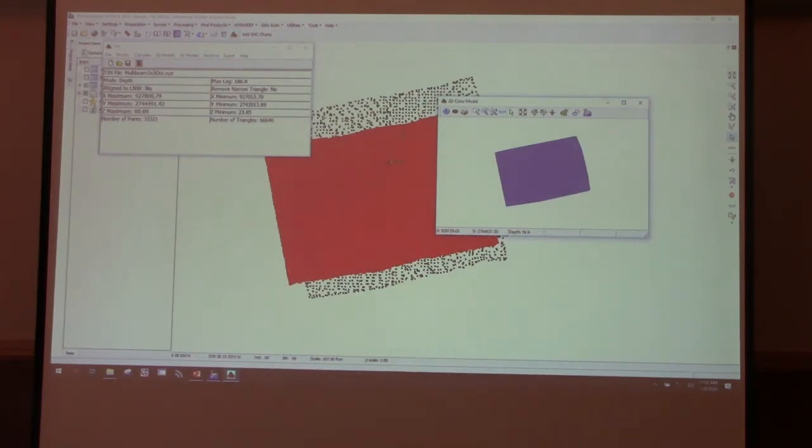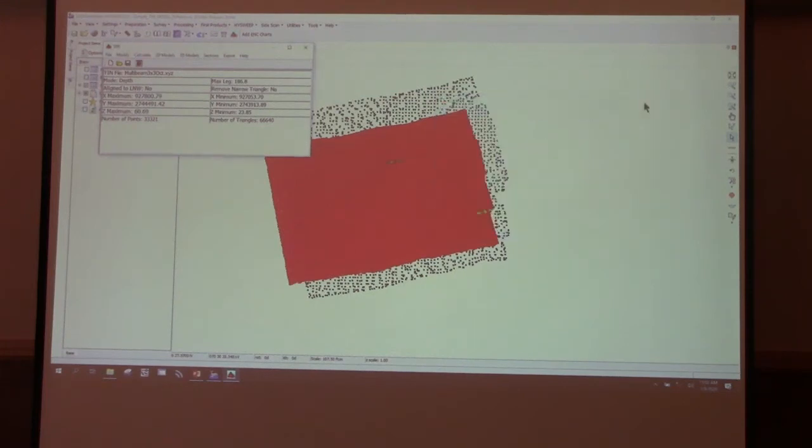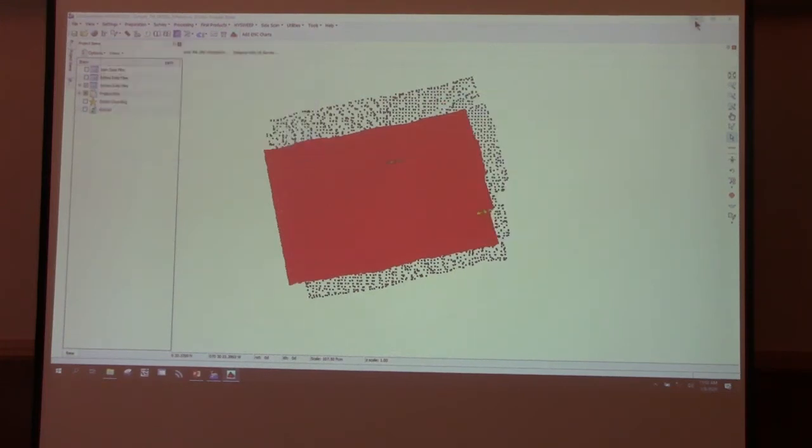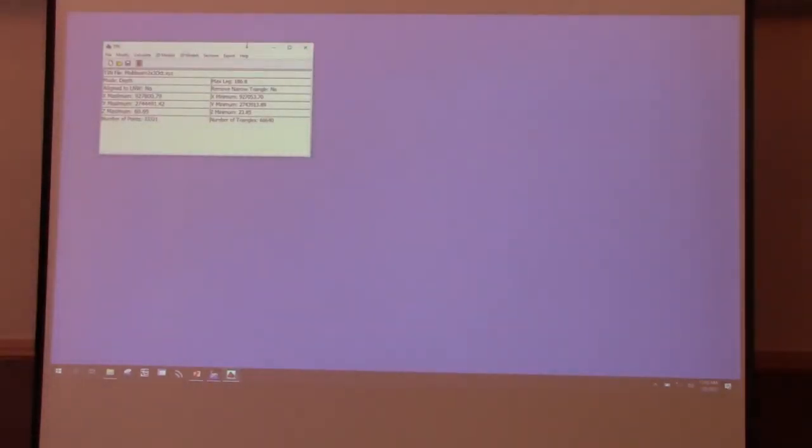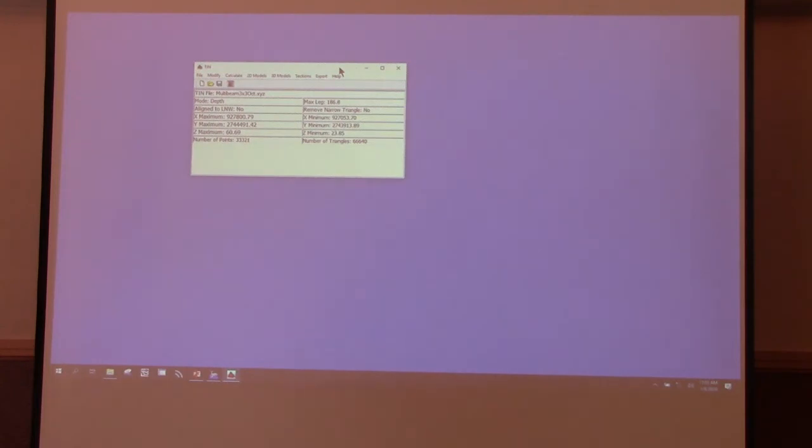So ideally, in my workflow, I typically want to use a border file and not even bother with the tin max side. I want to generate a tin inside this shape. So you might want to try to use it without any number in there and just let it generate on its own. Or if you're using a border file, and that's what his question is, there are some areas where he needs narrow triangles that don't get generated because he can't use the huge tin max side, can't use a little tin max side because he doesn't know which one to use, but he wants those long triangles.